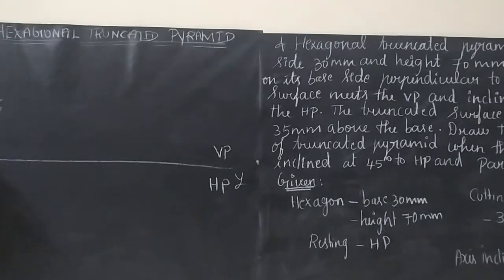Actually once the solid is cut, we will be getting the sectional top view here, right? So we will be representing. Just try to extend these points vertically, and we need to draw the slant edges, which is very important. Pyramid means we have to concentrate on slant edges, so we just join OB, OA, OC, OD, OE, OF.